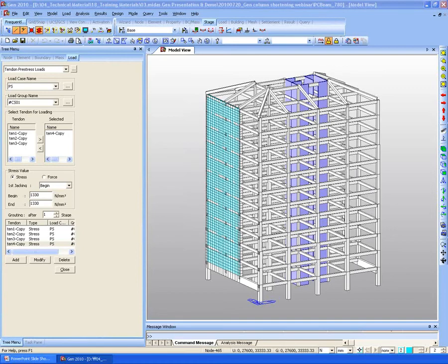For the lateral load, there is another question if we can enter the lateral forces during the construction stages. Yes, we can consider the lateral loads as well. By entering them as beam loads or nodal loads, we can activate or deactivate them during the stages. Only the live load, wind load, or seismic load will be entered in the post stages.